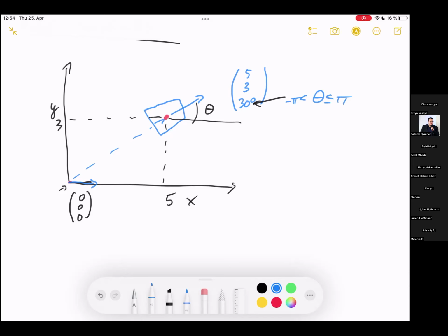And we don't say it's between 0 and 2 pi, but rather between minus pi and plus pi. The convention is that here we put a less than sign and here a less than or equal to sign. And when your robot rotates, always make sure later that its angle stays in this valid interval, and that not suddenly, if you keep rotating and rotating, your robot has like a 30 pi angle or something. That's what we don't want.